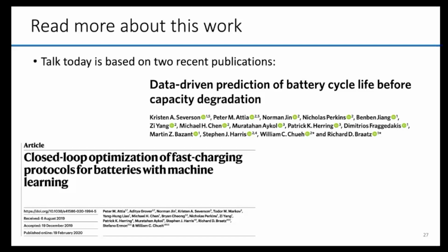Right. I think we've touched on this one, and the question probably goes back to what are the degradation modes of the different chemistries. So we really think the predictive power of the feature is related to the fact that the degradation mode is the loss of active material in the negative electrode, delithiated negative electrode to be specific. So if that is also the degradation mode for other chemistries, we have at least some reason to believe that the feature would be predictive.